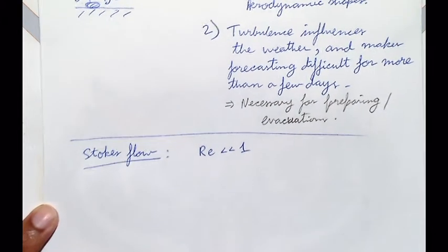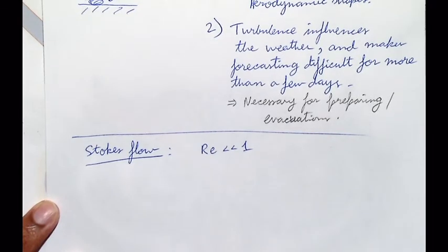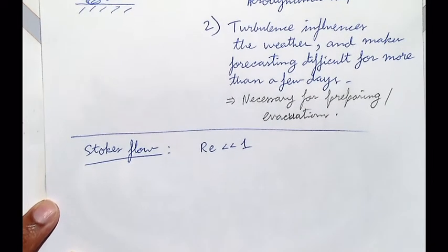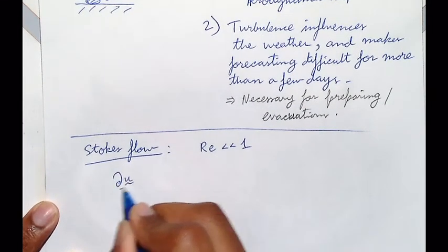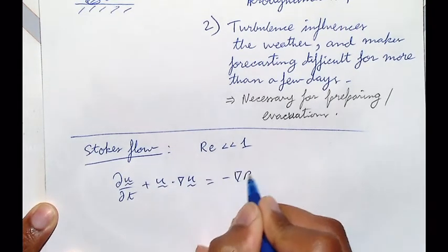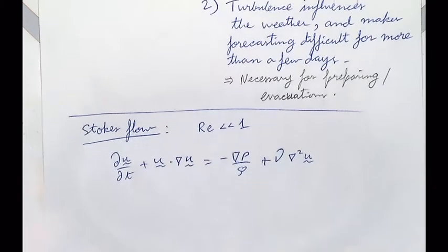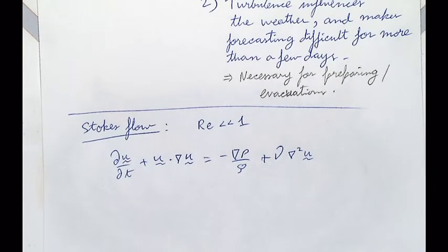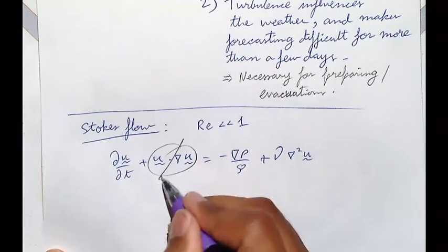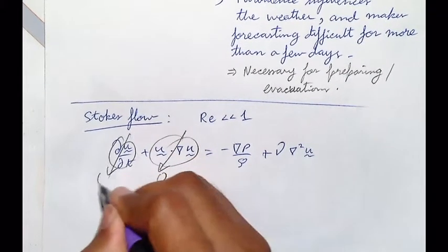All right. And so the equation looks like this: ∂u/∂t + u·∇u = −∇p/ρ + ν∇²u. Which term is very small and negligible? The convective term? Yeah, so we'll say this term can be kicked out, all right? And we can also say we will look at steady state.